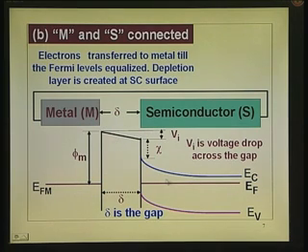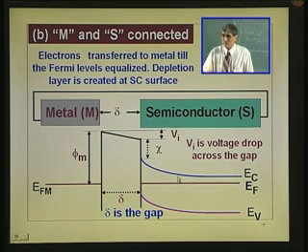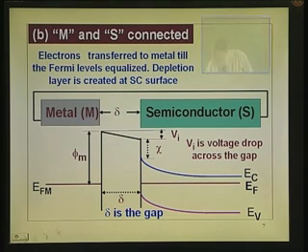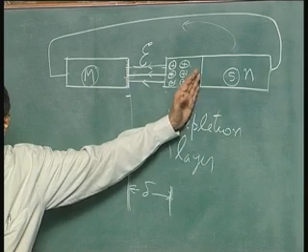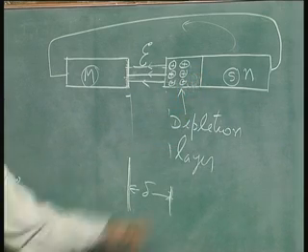And you can see this particular portion here, that is not linear, because you know that whenever there is an abrupt junction, wherever there is a depletion layer, the voltage is square law. So that is what is shown by this portion. So you got the voltage change here, that is shown by the change in the conduction band variation, and beyond a certain point it is flat, and it is flat beyond this portion. Because this is neutral region, there is no voltage drop. When there is no voltage drop, band diagrams are flat, that is shown in that portion.